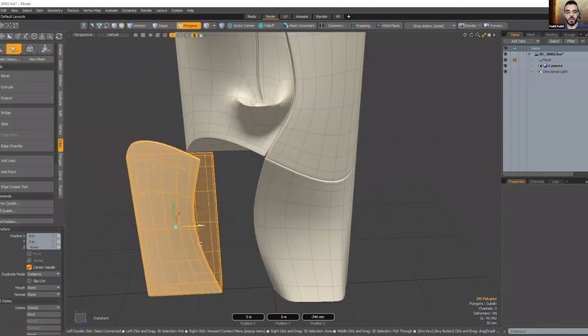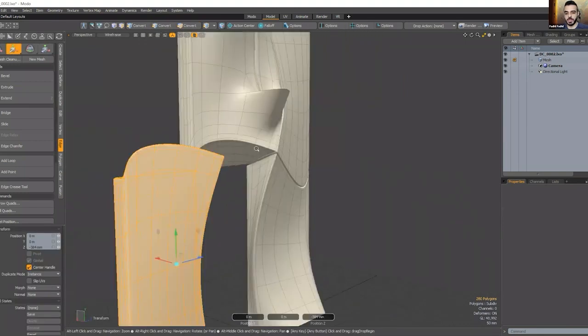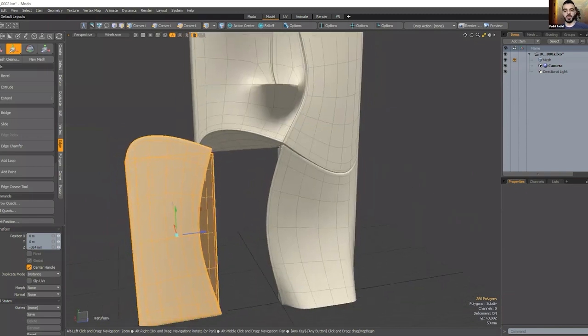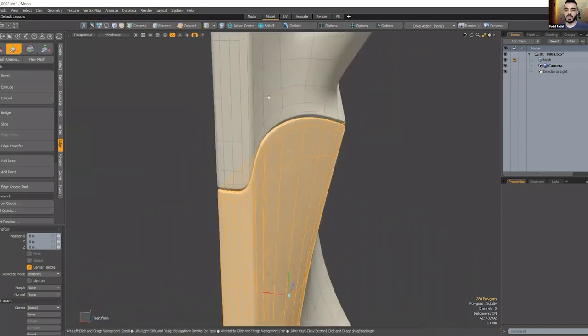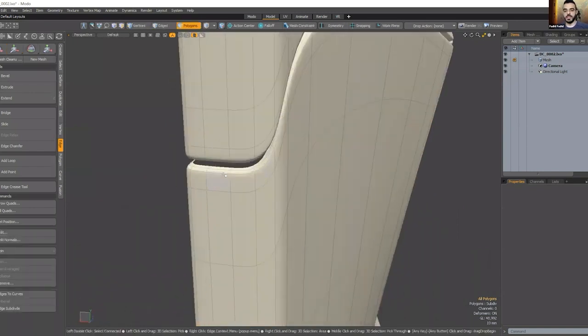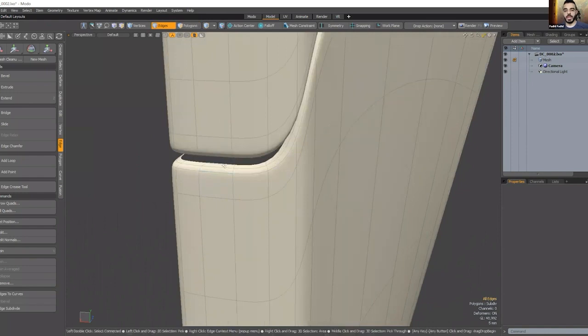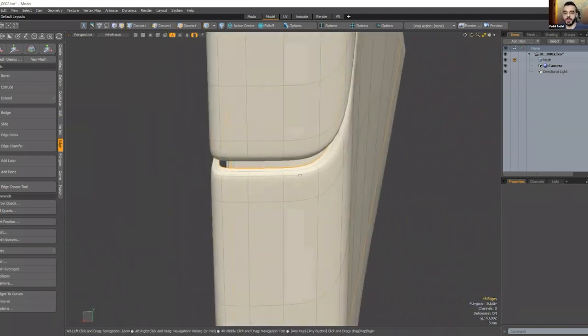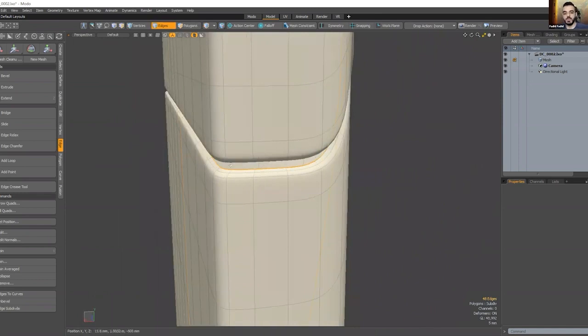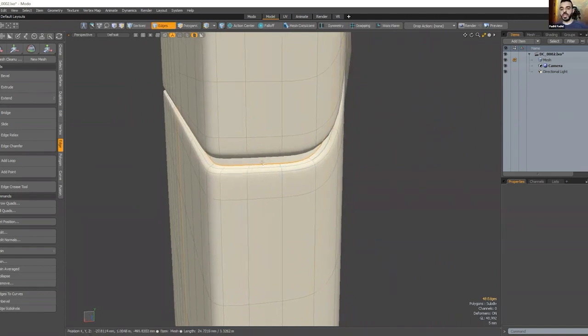So you see, once you delete the polygons, the surface is open, but the other ones are closed because I closed them a little bit ago. So I'm just going to close the surface so you know how to do it. Basically, it's another way to close off the surface using the edges. If you press number 2, you double click on the edges of the polygons that are open. And all I need to do is fill the space in between that's open with polygons. So I need to bridge the edges that are in between, but you can't bridge things that are already connected. So we have to make sure that our selection has gaps.